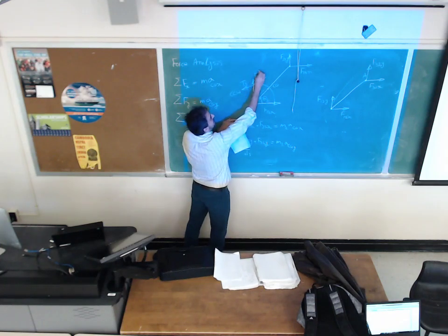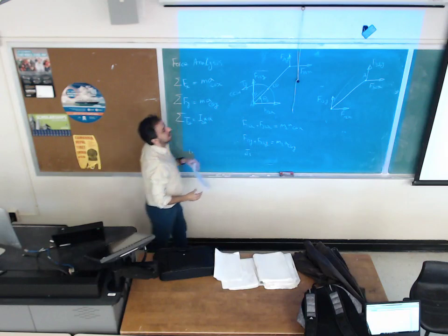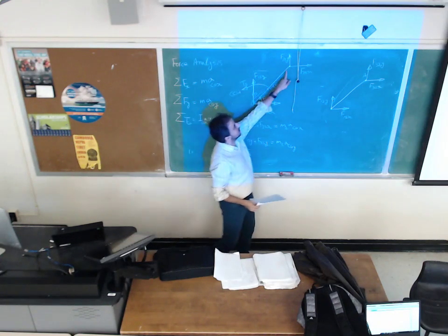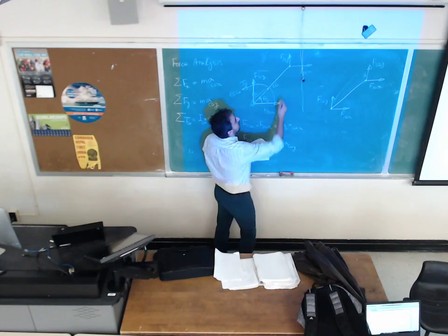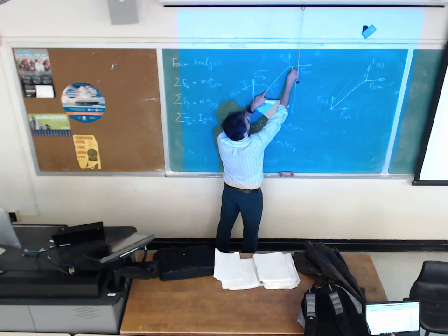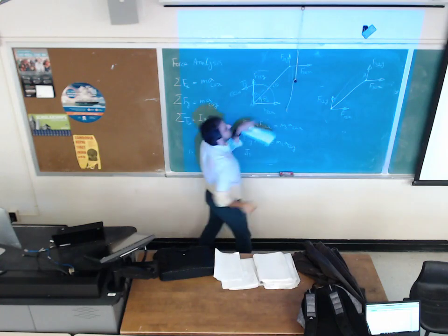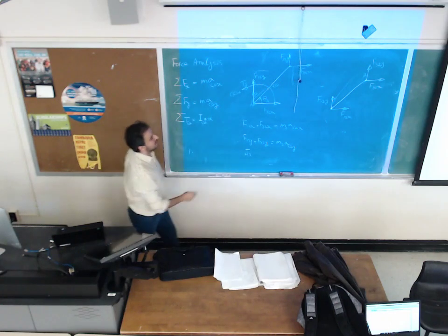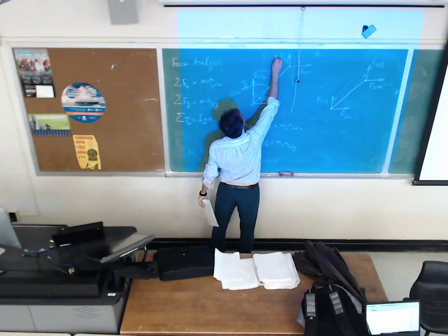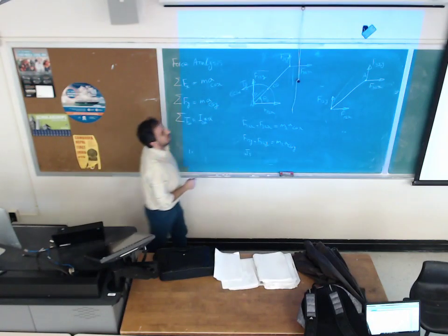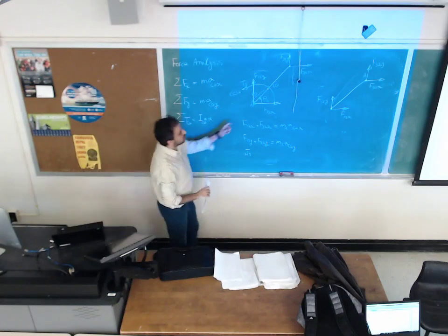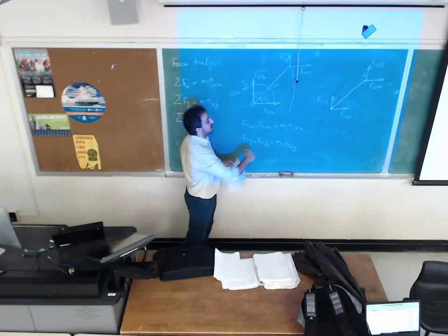This force is going to have this distance from the center of gravity, and this force is going to have this distance from the center of gravity to make a rotation about that. So what I need to do is find the moment that each force is making about center of gravity. And I should be careful about the sign.